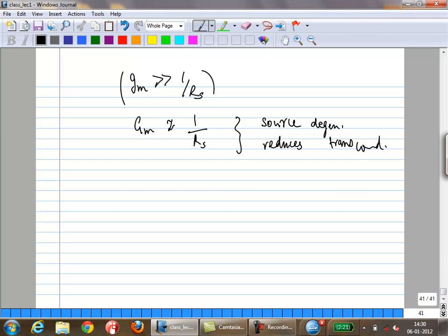So there are a lot of ways to look at this circuit. So if we just take this circuit, right? Another way to look at it is, you can look at the signal going from here to here as some kind of source follower, right? So in other words, you could say Vi by Vs is approximately 1.